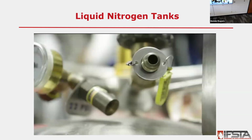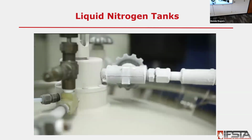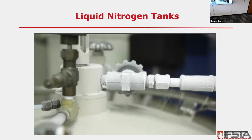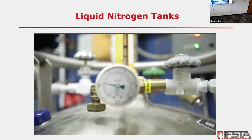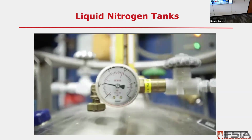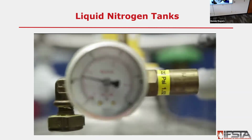The primary pressure relief valve opens at the lowest pressure and regularly vents excess gas. A slight hiss from a liquid nitrogen tank indicates normal operation of the primary pressure relief valve. A small gauge installed on the cylinder may show the pressure inside the tank. This gauge reading should be equal to or less than the setting of the primary pressure relief valve.